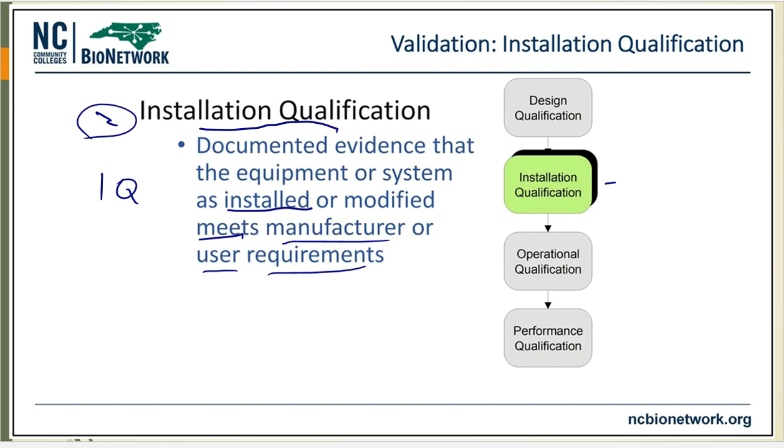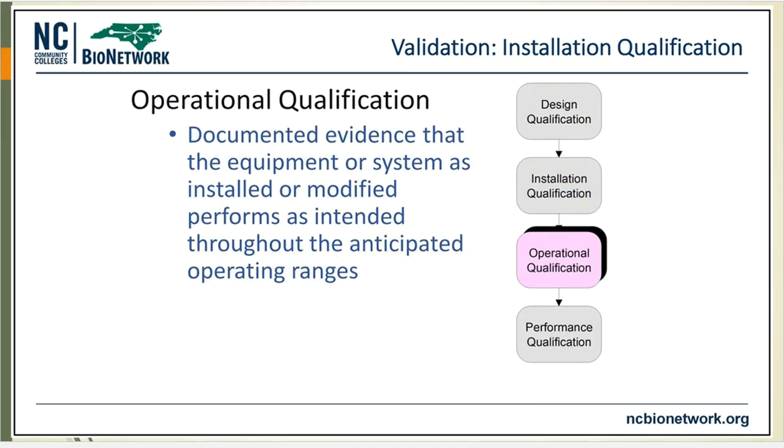All right, so design qualification: the company's made something to certain standards, and that's appropriate for me, so I'll order it. That comes in, so people are going to come in and install this piece of equipment, whatever that equipment might be. Again, it could be bioreactors for all I care. It does not matter. It's a piece of equipment. So they're going to install that bioreactor, or something else that you're using, like a drum filter or whatever the case might be, and they are doing some self-checks to make sure everything's working according to plan. Next up is the operational qualification. They will often abbreviate this OQ.